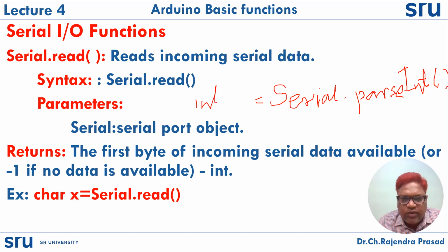So in this case, it will read integers. Let us consider int x is equal to Serial.parseInt, but with Serial.read it will read the characters. So based on our requirement, you can use either parseInt or read.